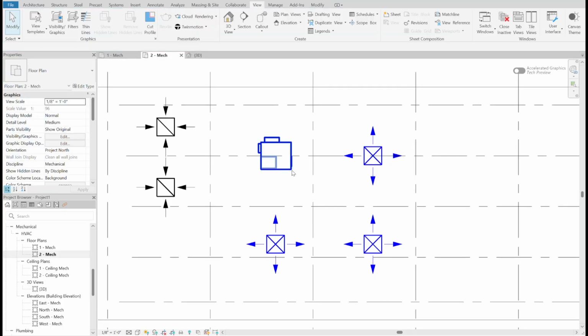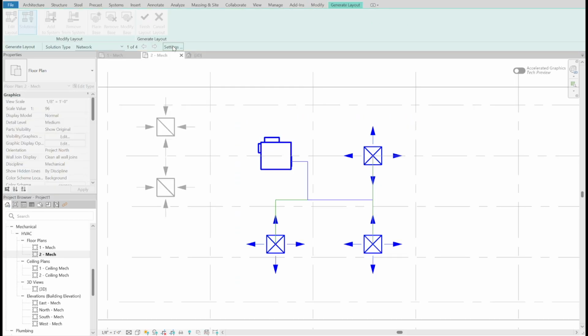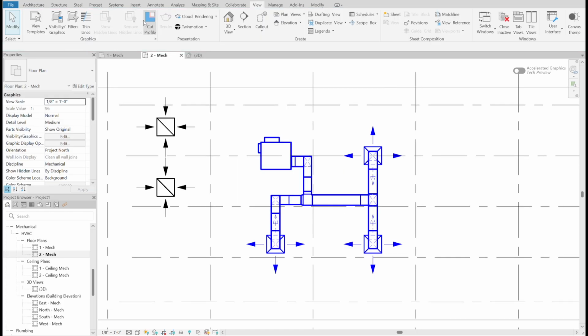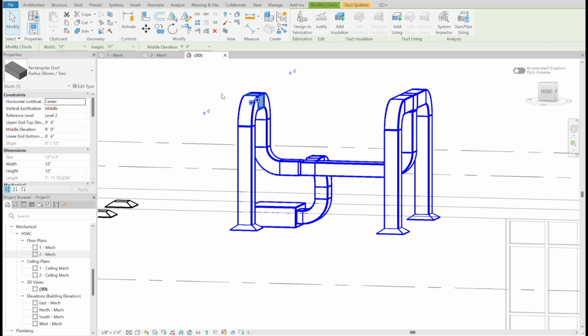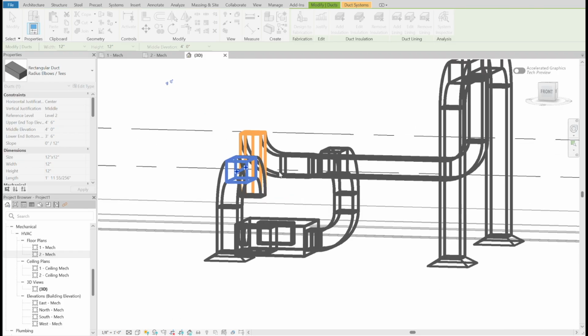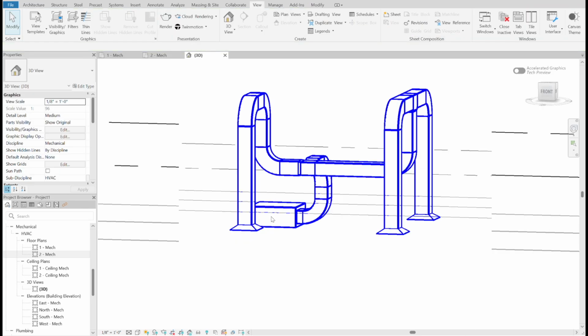Okay, so the other way of doing that is when you are generating the layout, there's a setting, and you can define, I want my offset to be 4 instead of 9. And it can generate the layout based on the need. So there's still something we need to correct, but we can manually correct them later. And of course, if you change the design, it'll give you some trouble like a disconnected pipe, then you have to manually correct that. So let's go back for now.